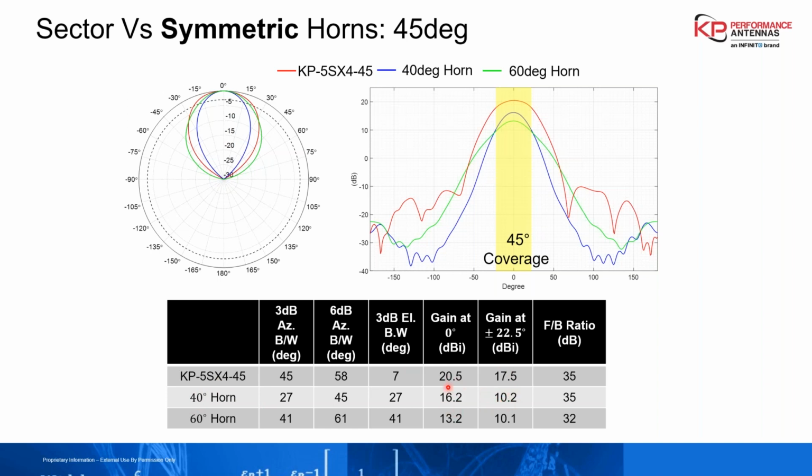Whereas a sector antenna is rated for a 45-degree beam width, and that's with respect to the 3 dB beam width. So if the sector antenna is 20 dBi gain, at the edge of its sector the gain is only 17.5, which is not that much of a drop-off. We're talking about 1/2 the power versus 1/4 the power dropping off.